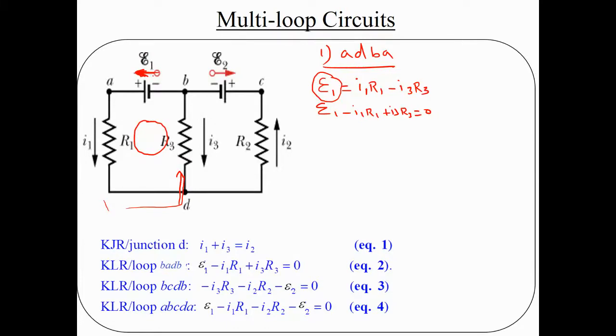Now see, this red color sign is given. That means the main current from the battery is going like this. You have to compare the remaining currents with this red arrow. The red arrow is in this direction, and my I1 is also in the same direction as the red arrow. Am I right? Yes, same direction, so it has a positive value. Now let's come to I3. My red current will be coming in this direction, but my I3 is in the opposite direction. Am I right? Yes. So what sign should you put?